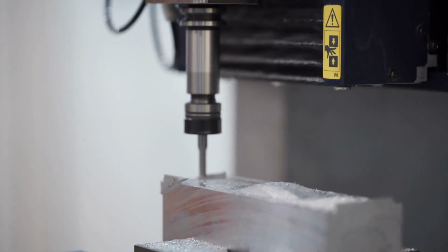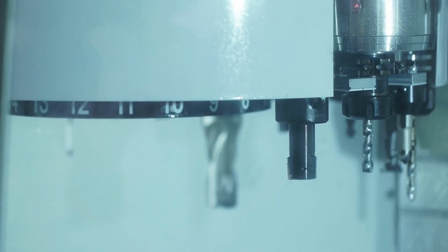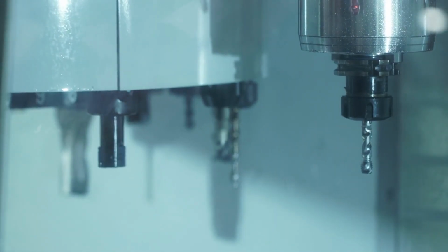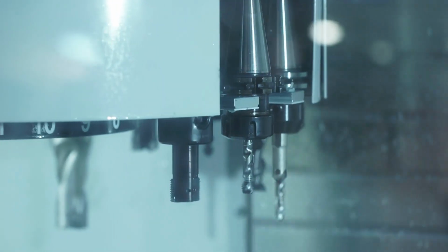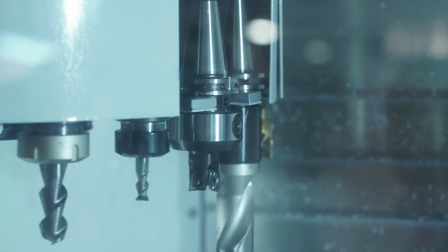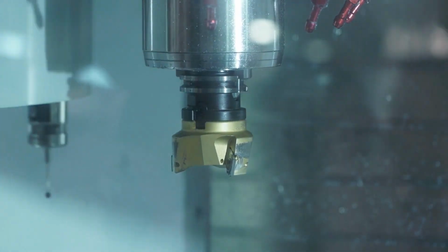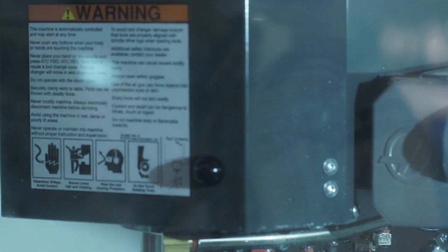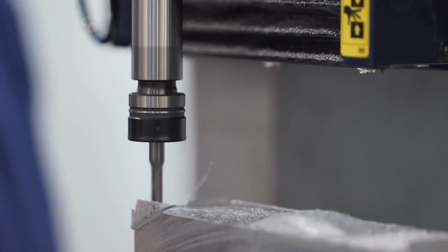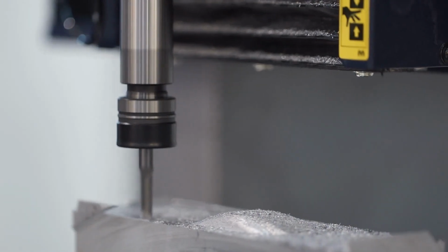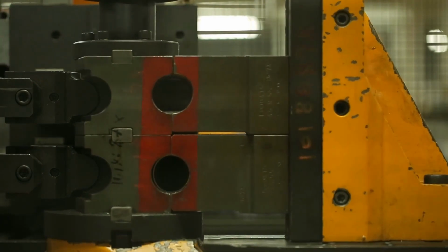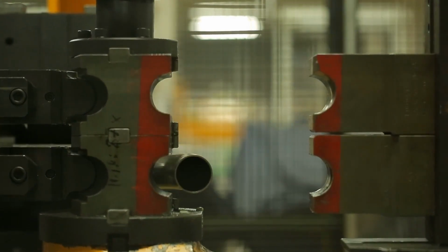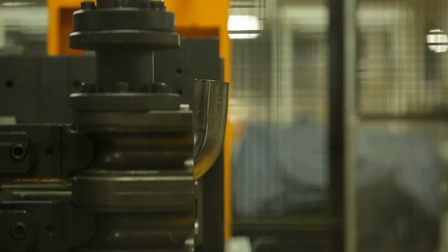Choosing an origin point for your WCS requires some careful planning. Keep these points in mind when going through the process. The origin will need to be found by mechanical means with an edge finder or probe. Repeatable origins help save time when swapping out parts. The origin needs to account for the required tolerances of downstream operations. There could be another full blog on selecting the most optimal origin point, especially for each subsequent setup as the tolerance stack-up begins to grow. Make sure you keep in mind the tolerances of previously machined features, your locating mechanism, and your machine to ensure your final part is to spec.